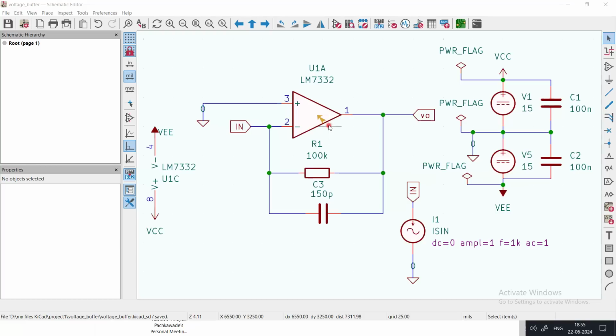So we'll perform a couple of analyses and we'll see how our input current can be converted into a proportionate output voltage set by the resistor gain. Not necessarily should you choose only 100K. You can have any value that is required for your application, okay? But accordingly then you have to choose the gain bandwidth product, do some calculations, but that's not the focus. We have also covered those parts in theoretical lectures in our library.